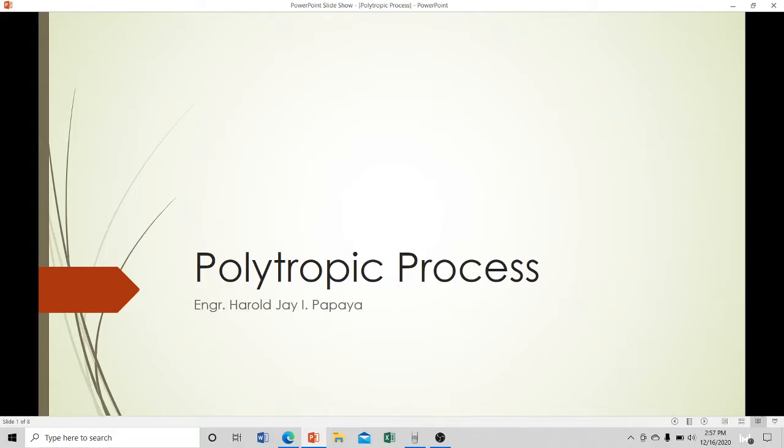Hi guys, in this video we are now talking about the polytropic process. The term polytropic was originally coined to describe any reversible process on any open or closed system of gas or vapor which involves both heat and work transfer, such that a specified combination of properties was maintained constant throughout the process. In such a process, the expression relating the properties of the system throughout the process is called the polytropic path.